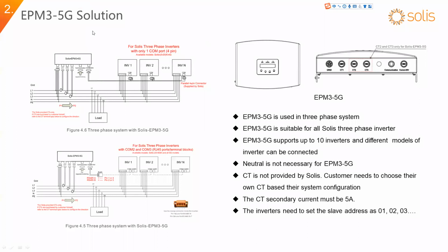Compatible with genset connection? As I just said, we haven't tested the EPM with a genset connection. Maybe the control speed is not fast enough to maintain zero backfeed into the generator, so you may need a third-party controller to provide this faster control.